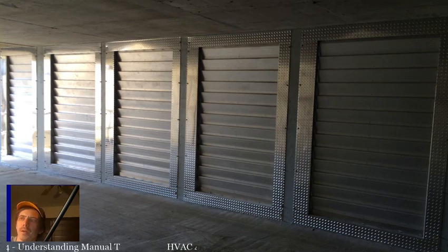But on those natural draft appliances, you won't have inducers and pressure switches and things like that to prove the draft. So you need to prove that draft manually, semi-regularly, to make sure that everything's working right, because there's a lot less safety devices to help you in case there's a failure on that equipment drafting. So just understand the components that are not a part of natural draft equipment, as opposed to induced draft equipment or 90% direct vent equipment.